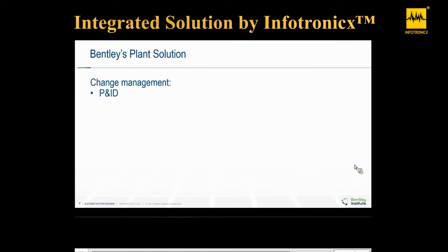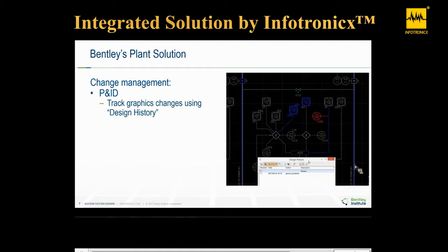So meanwhile, one or more copies of a P&ID can exist in some form of proposed state, in-house or at a contractor site. The changes to this P&ID can be done well ahead of any plant physical change, and the owners need a way to visualize these proposed changes against the current set of P&IDs. Using OpenPlant P&ID, the changes are tracked automatically and embedded into the document to be reviewed between any two versions. So in this example, we see that the color-coded set of changes are captured between the new, deleted or changed portions of the P&ID.